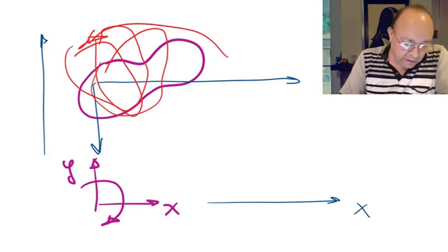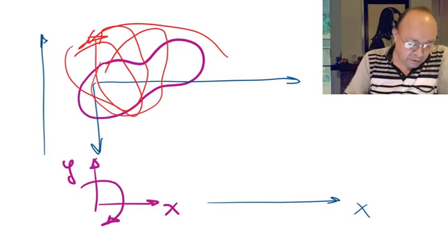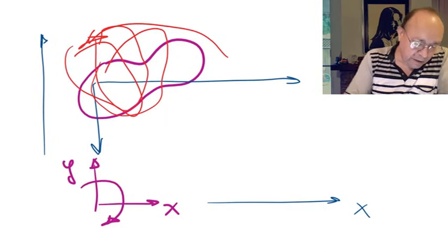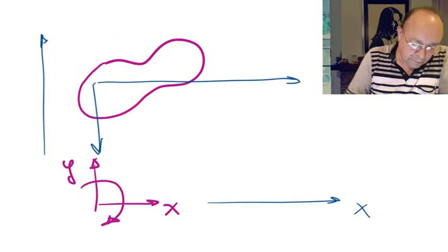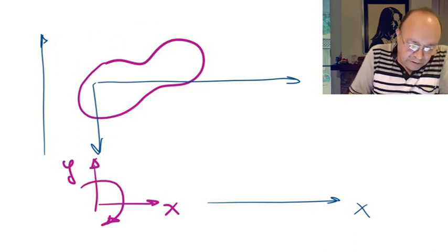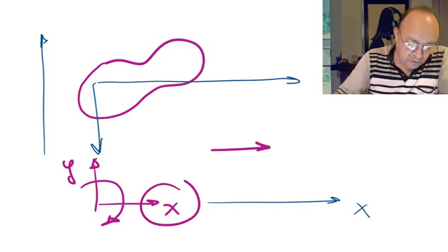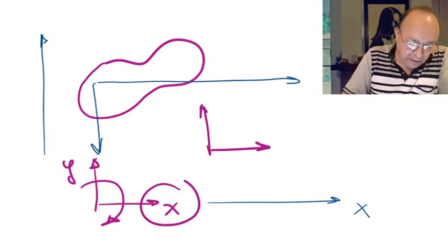So in order to guarantee that there is no rotation and no translation, what we have to verify are these three concepts: no forces in the x direction, no forces in the y direction, and no moments.